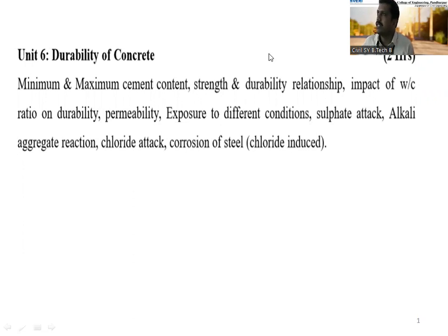I have two answers for this. Definitely yes, this is my first answer. And no, this is the second answer. Why? Because depending upon the mindset of the contractor or the engineer, whether he is going to follow all the legal practice of construction as per the standard norms, we don't know. If he does some malpractice in the concrete mix design, or at the time of execution, or maybe some corruption in purchasing the raw material, poor quality raw material, then we can't predict the structure will be durable.